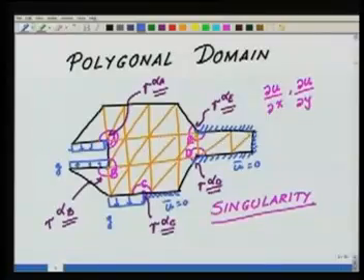It is represented in terms of a mesh that we put and the approximation which goes with the mapping that we use. So if we use this linear mapping, then this fillet will be represented by these corners. So even though my actual problem does not have a singularity per se, though it has a stress concentration, the problem that my finite element formulation sees is a problem with a singularity, and that's what it tries to solve. Okay, and for that we are still going to get the same problem as we have outlined.